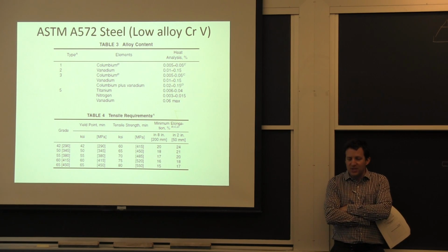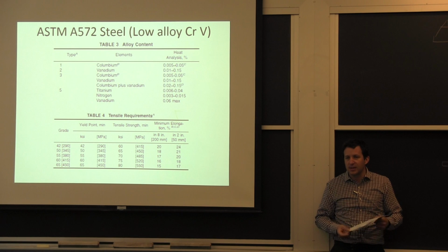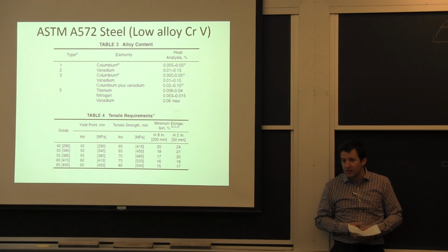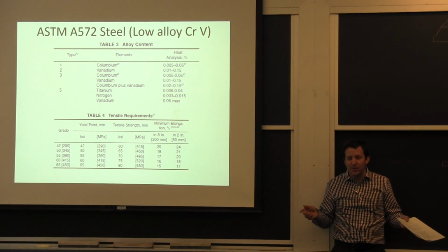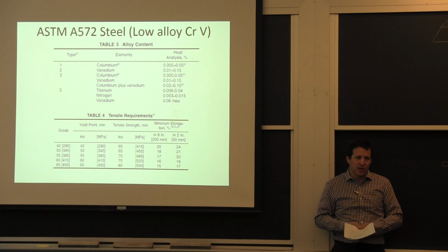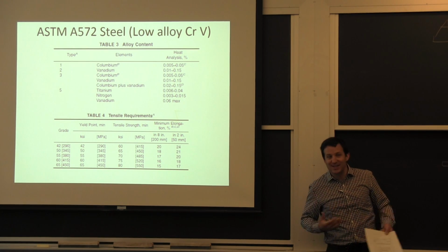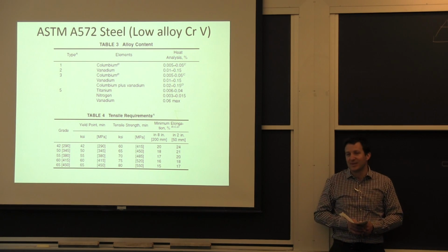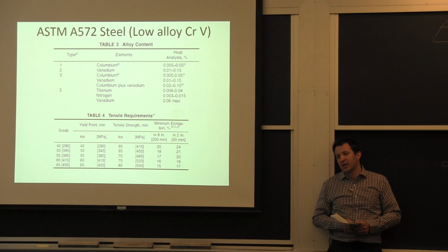The spec tells you to test it with the extra anodizing, but I didn't want my properties to be lowered, even though I knew that the aluminum properties were actually higher, and that's why I took it off. So when I ran that test, I didn't meet the ASTM specification. I did it my way. So I wouldn't be able to say whether my sample met the ASTM specification or not.